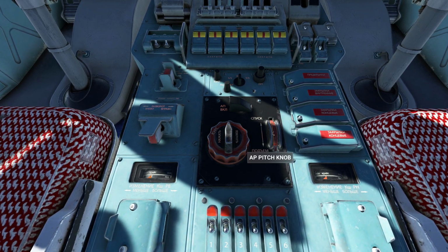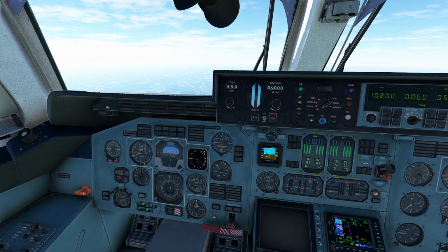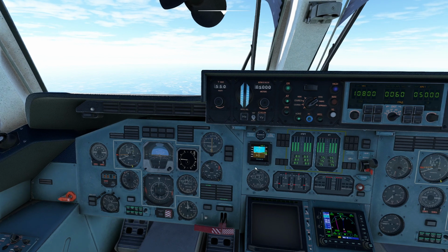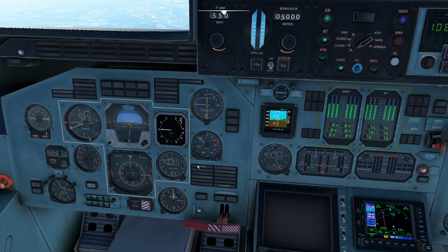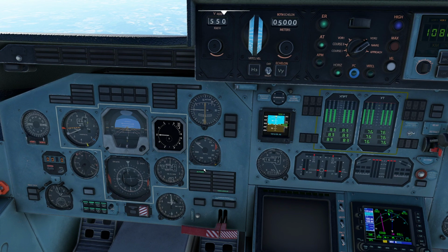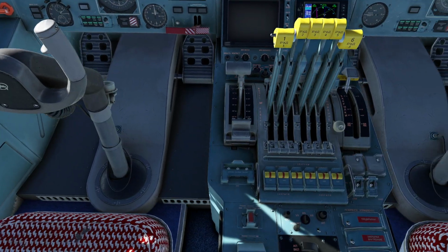So let's say, for example, I want to order a climb. I could sit here and give this thing a couple little wiggly waggles, and what will happen is the nose of the aircraft will pitch up. Of course, you're taking a look going, hey, why am I not getting altitude? Because we're currently on altitude hold mode. So what we have to do is actually disengage that mode in the event that we want to cause it to do a specific thing. You'll notice, by the way, I tapped that button twice. It locked onto the new altitude very effectively. Not really what I wanted it to do.